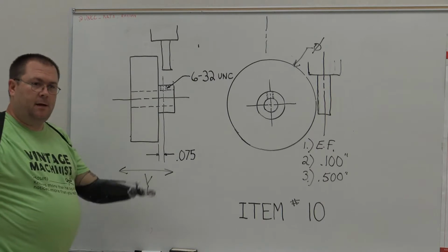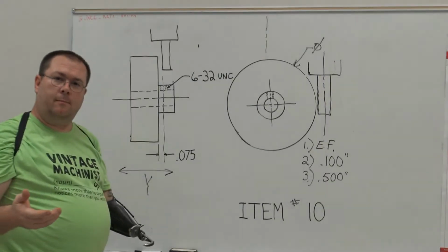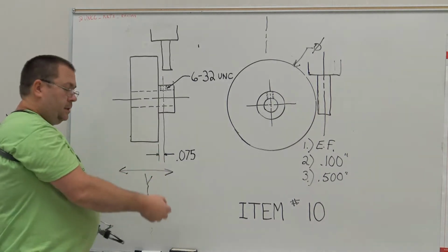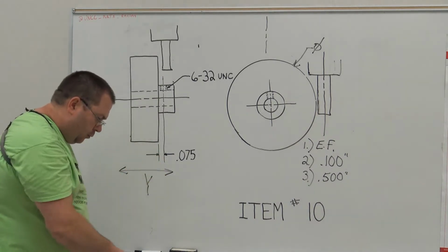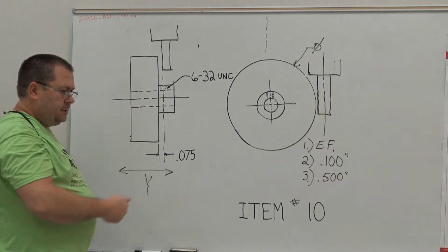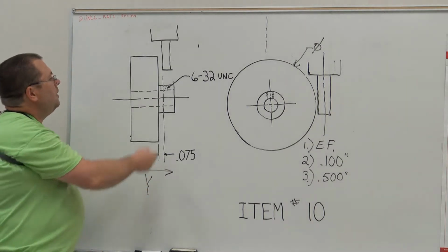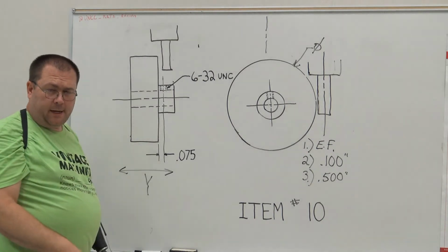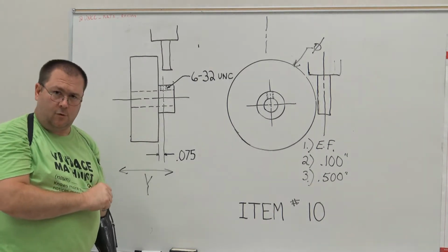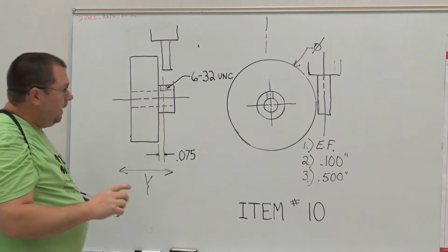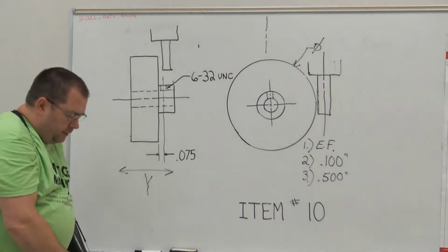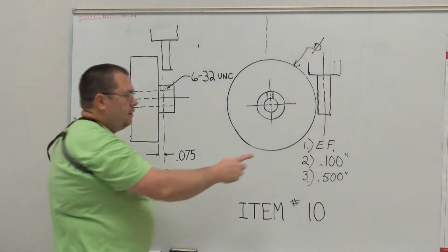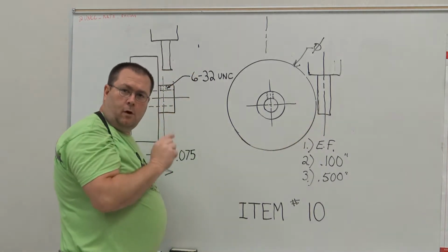We'll start the machine up again at the max speed that our mills will go downstairs. We're going to take our y-axis, which is the handle right in front of me as I'm standing in front of the milling machine. I'm going to feed in until it just kicks off my edge finder. Again, nice and slow so I can control the accuracy. At that point, I'm going to reset my dial to 0. Now, resetting my dial to 0 is probably something I didn't go over here.